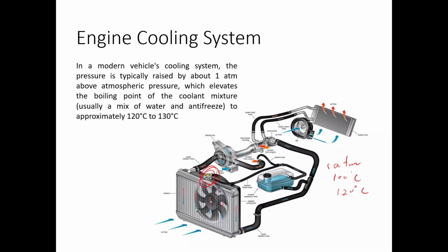Otherwise, what you have inside is high pressure liquid, and when you open the radiator cap, the system pressure suddenly drops. At that point, your water evaporates. I mean, the water boils off very fast, and then you can get burned. That's why people normally say don't open the radiator cap until the engine cools down. Those are some of the applications, right?